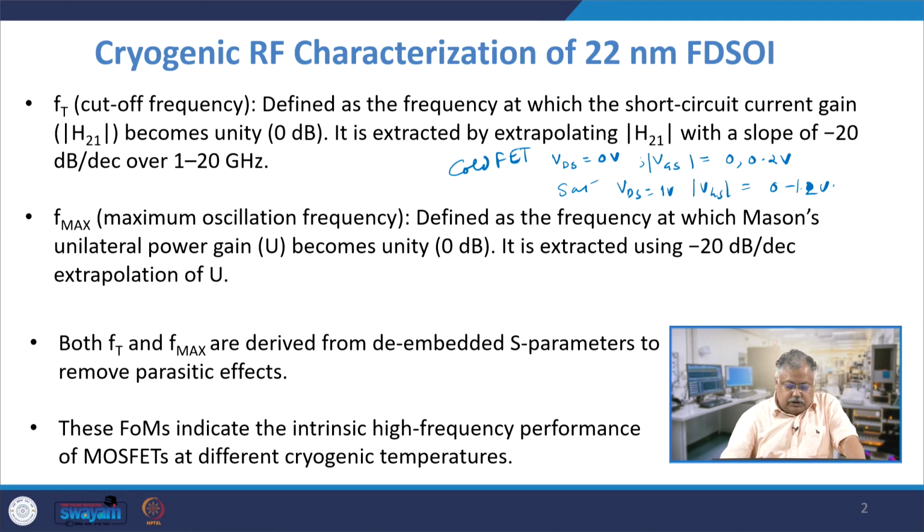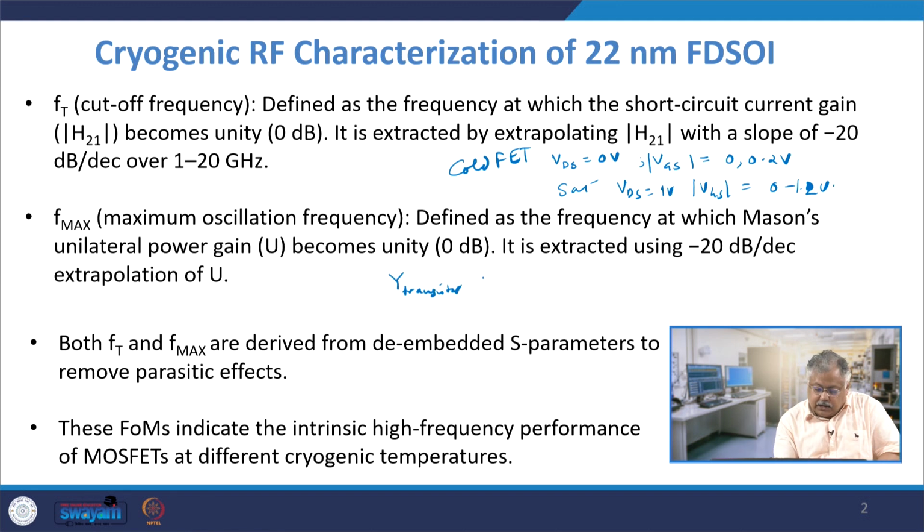The S parameter of the on chip open and short circuit currents are measured in this paper for all the temperature ranges, and they have done a two step de-embedding technique in this case for extracting the value. What they have found out is that the series combination of interconnects will give you Y short minus Y open. So, the Y parameter of the transistor is effectively equal to Z device under test minus Z series to the power minus 1, right, minus Y open circuit.